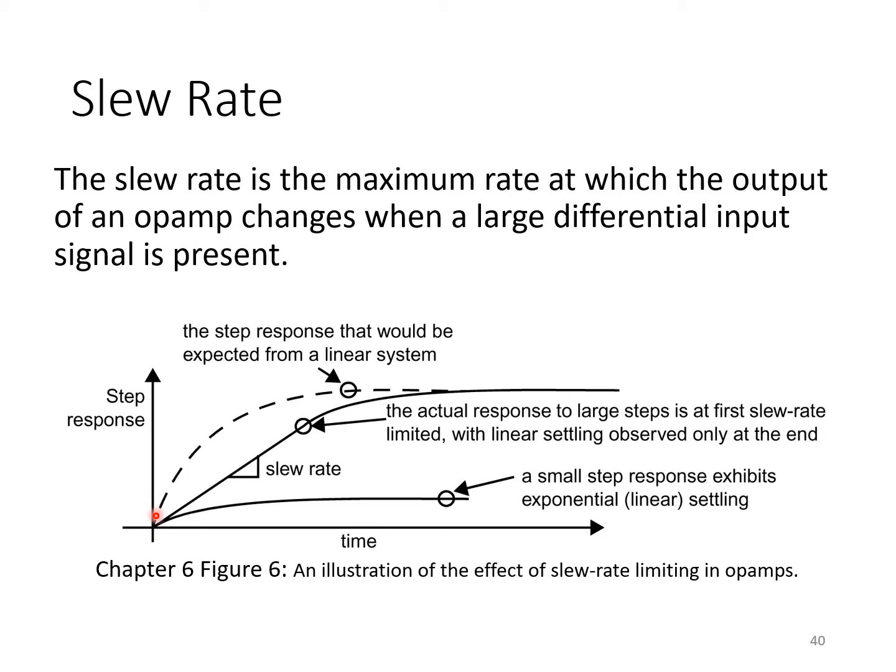And that rate of change may require capacitances in the circuit, or perhaps at the output node, to be charged or discharged quicker than the op-amp is capable of. Usually this is because some bias currents are being fully used up just charging or discharging a capacitor, leaving nothing to keep the transistors biased at their proper operating point. So something inside the circuit likely saturates. In any case, the slew rate sets the limit on the maximum rate of change at the output.